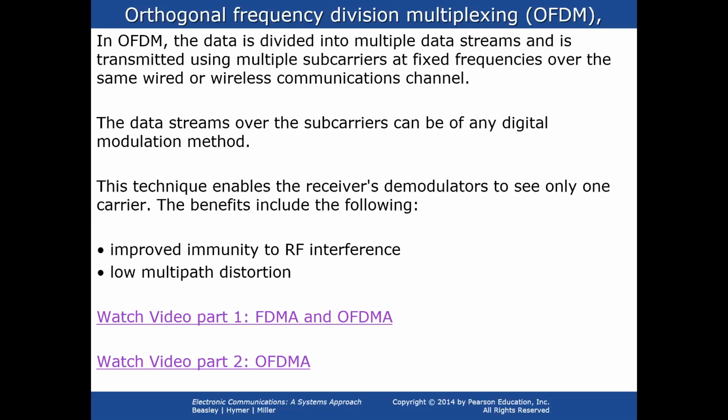In OFDMA, we have one-to-one mapping between symbol and subcarrier, but SC-FDMA allows the symbol to be transmitted in parts over multiple subcarriers. For example, in OFDMA, one symbol occupies one subcarrier of 15 kHz, but in SC-FDMA, the same symbol is distributed among multiple subcarriers of 15 kHz. In short, SC-FDMA behaves like a single carrier system with short symbol duration compared to OFDMA.